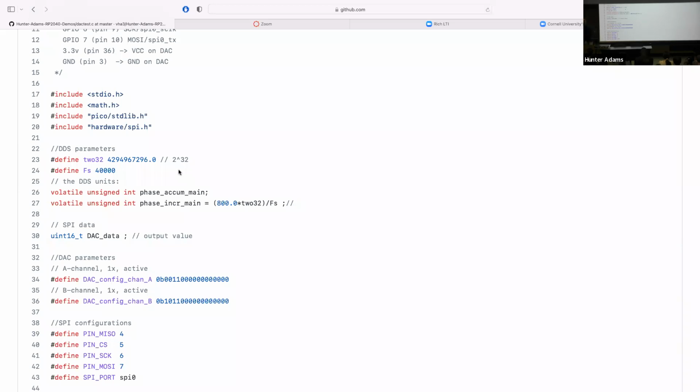And sometimes they couple, right? So for instance, maybe you want to learn about the timers because you want to set up a timer interrupt service routine. So you read the timers chapter, and then you say, oh, I should learn a little bit about how interrupts work on this system too. So you go read the interrupt chapter. But that's how I recommend approaching all this documentation, is sort of like that.